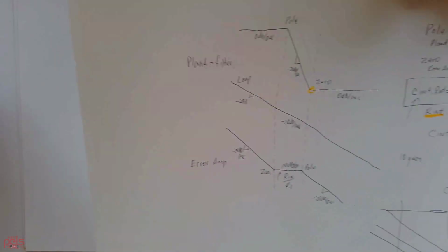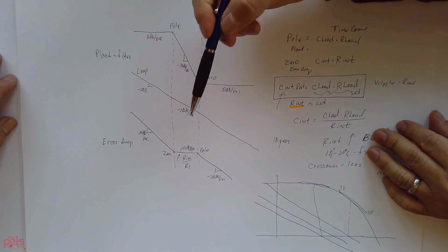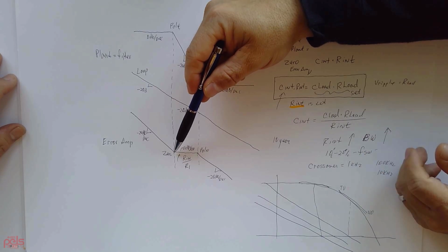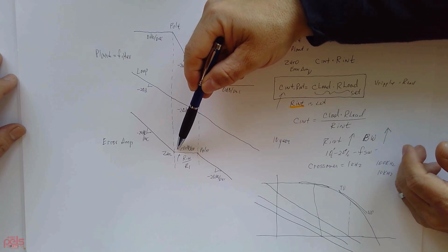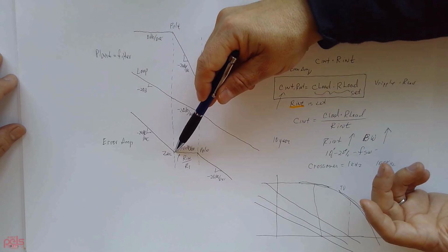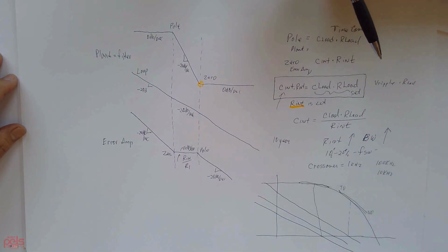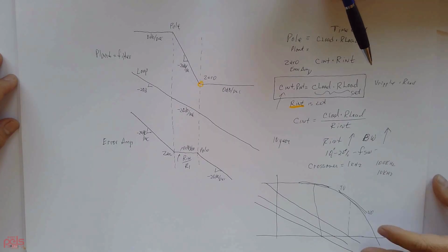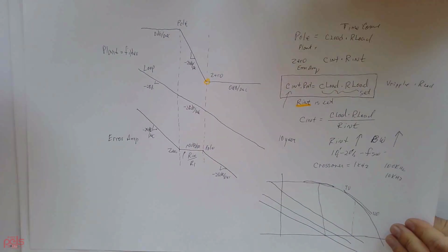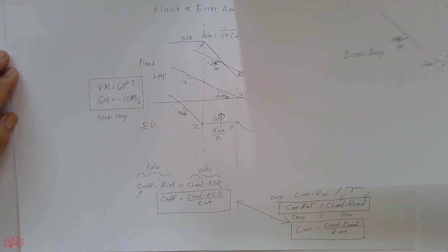So let me put this picture that we talked about yesterday again, which is similar to the one we had before. Let's say that I wanted to fine tune this zero, move it out a little bit, in the actual application. In that case, I need to keep the same time constant, right? Yes. Basically, if you do the pole zero cancellation, it makes compensating much easier.